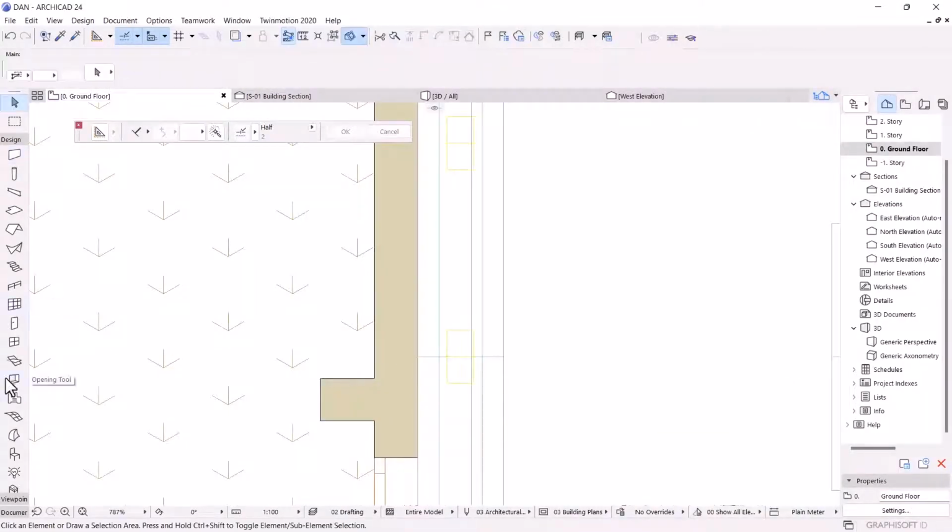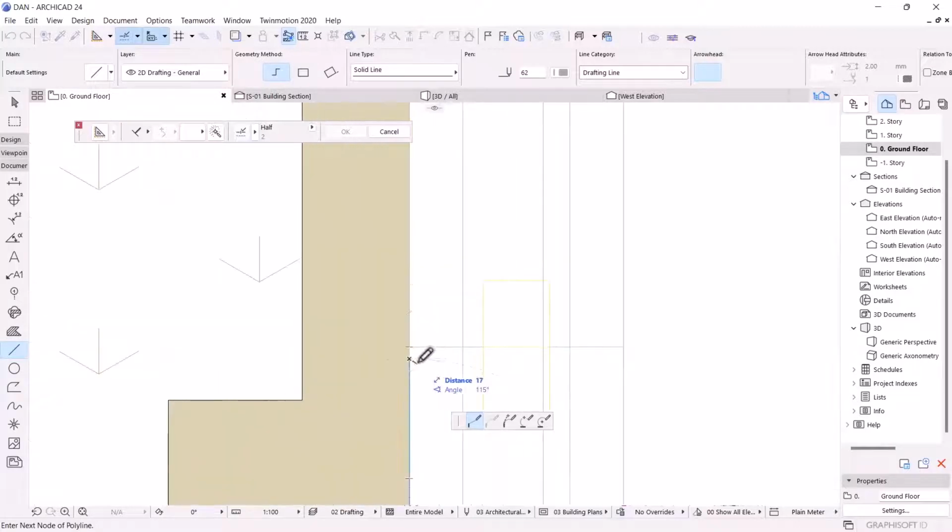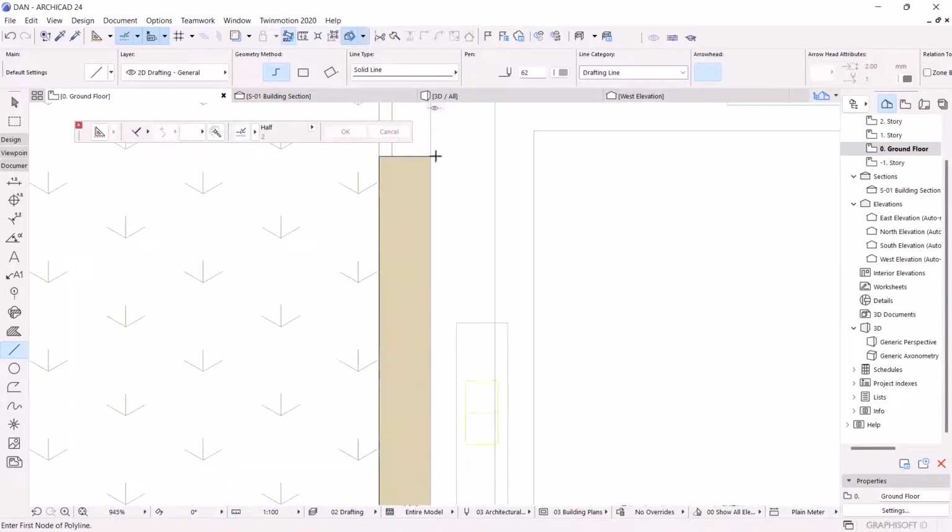If you have the line tool, then you come here, you point in this direction and you type 450. To this point, then you point in this direction and you type 450, and you draw a very short line there, like that. Then as well, I could have repeated the same thing on this end, 450, and a short line there like that.